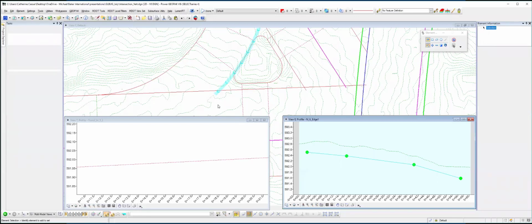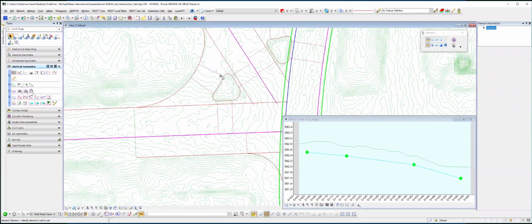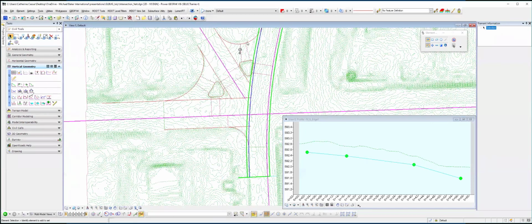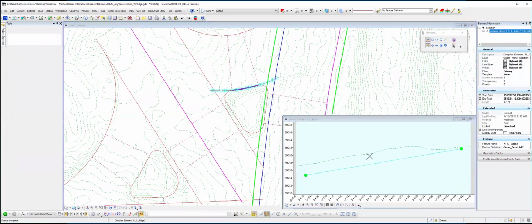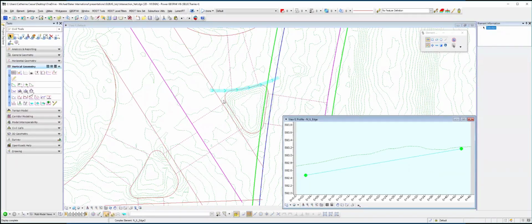That's one school of thought. And that works when you know you have to have very specific slopes across this element right here. The other idea, which is something I do more when we get to Michigan lefts, is to let this one inherit its slope directly from what's happening from here to here. So these 2 points here are where it's intersecting the edge and the edge.